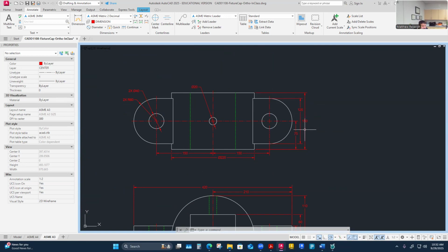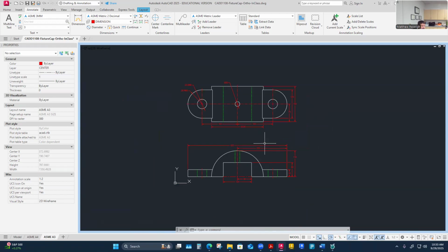It's more critical that the part is centered. That's why I've chosen these dimensions. Those are going to fall into place because it's just the difference of 120 to 150 split in half. So that's 30 divided by 2 is 15. So it's going to fall into place. And one reason might be that's not a critical dimension to even put. The part's purpose usually is what makes some dimensions more clear than others. And so in this case, I don't know if the 15 is really that critical, but I know that I'm able to figure it out. And actually, I feel like what's more critical is everything is centered up and symmetrical on itself. And my dimensions have captured that. So the 15 will just fall into place if I follow the rest of these dimensions.